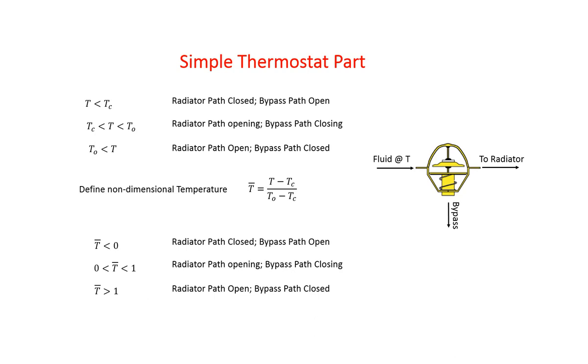During this exercise, we'll see how to define a complex part with two flow paths, inlets and outlets. We'll create a form with user variables for thermostat control, define the behavior, and finally assign an icon to our part.